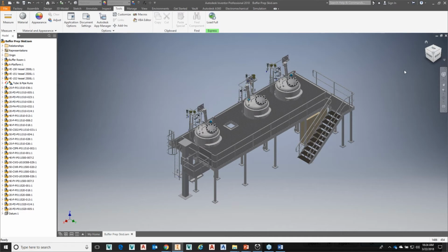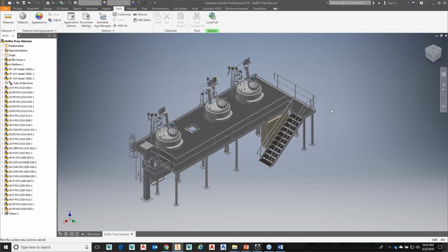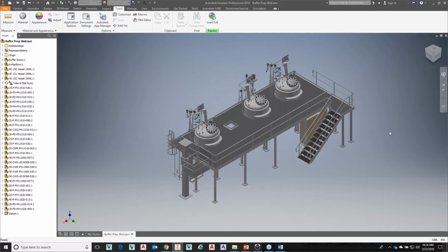So that happens immediately as opposed to me waiting for this thing to redraw slowly with my graphics card, drawing each iteration in between front to top to right. Okay, so normally when I'm just modeling a part, I don't like that setting, but in a large assembly, I'll take it, anything to work faster. So a couple more places where you'll see this benefit.